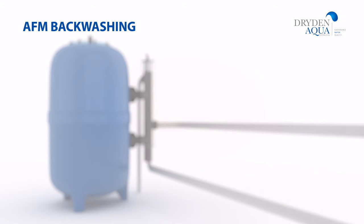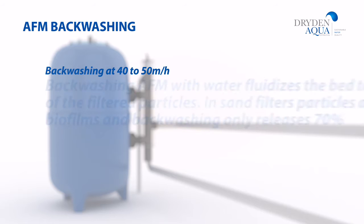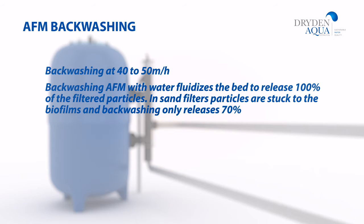During a backwash at 40 to 50 meters per hour, the grains of AFM are fluidized and 100% of the trapped particles and dissolved pollutants are removed. The best a sand filter can achieve is around 70%. Up to 50% less water is used to backwash AFM, and the media lasts for the life of the filter.